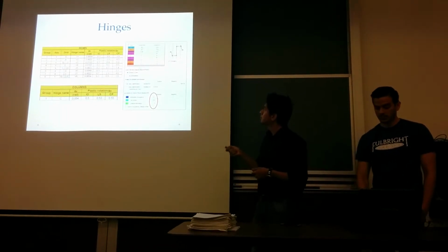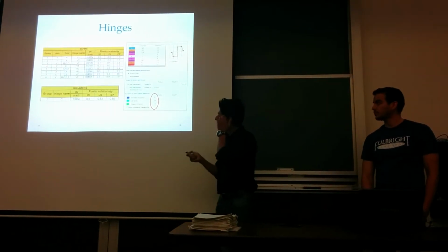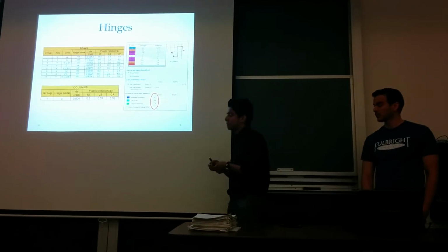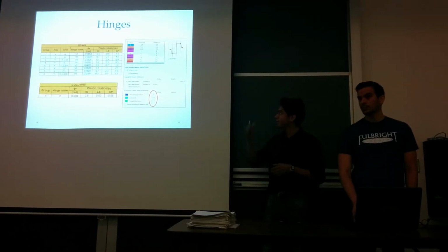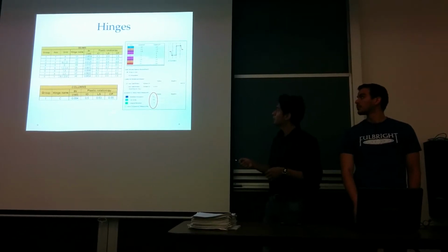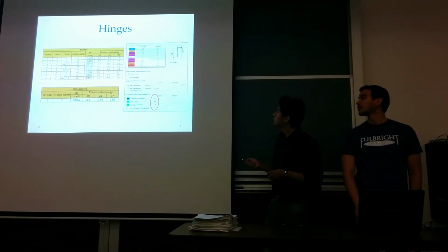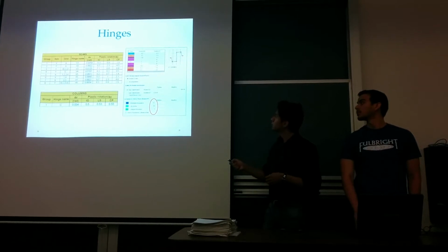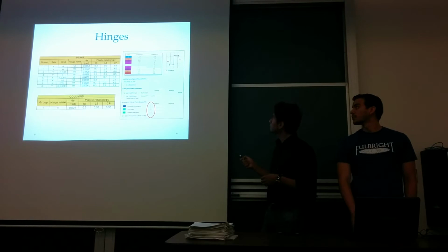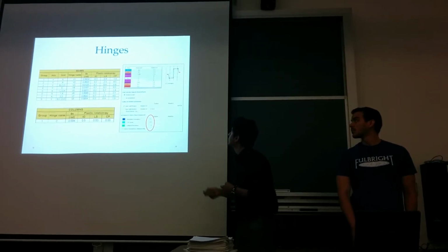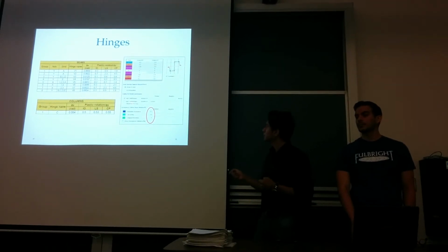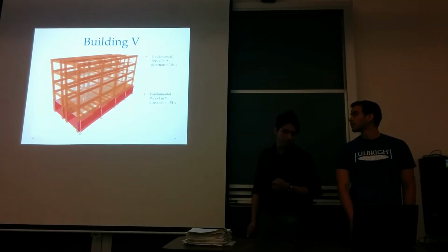And we calculated this yield curvature for each beam, grouping the beams by similar length and similar depth in order to reduce this calculation. And we did the same for the columns. We added this value in this way to get the load deformation curve for the hinge, and we normalized the acceptance criteria with this value.